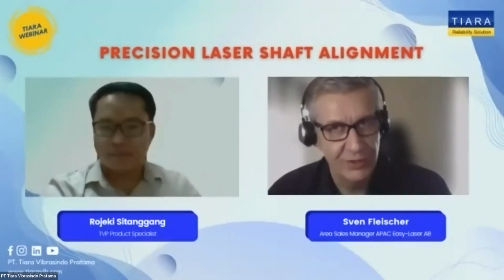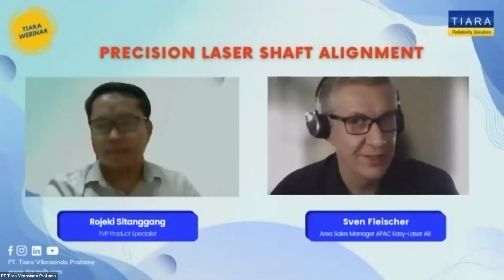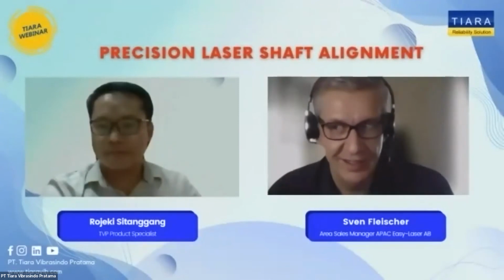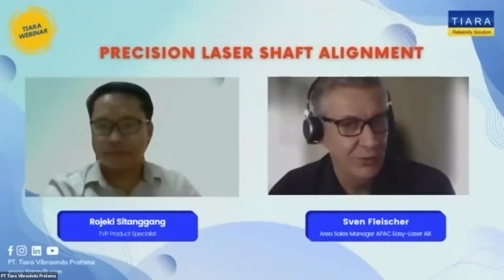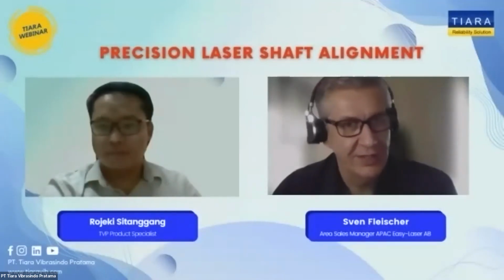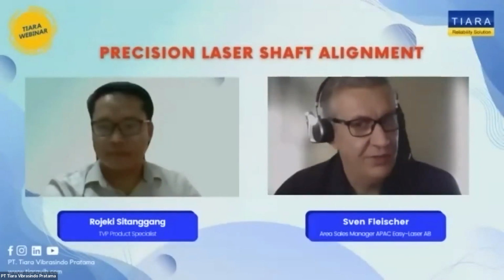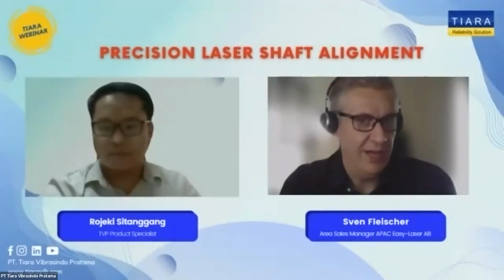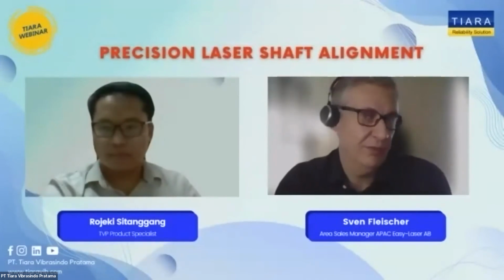Now, while you are correcting the machine, what is the purpose of the measurement instrument? It records basically all kinds of physical movements as you go towards a precise alignment. It would not know where this movement comes from. Is it from your machine correction, or does it come from another influence factor, which is a disturbance? This differentiation is not possible to make. That is then up to the engineer to recognize and then to compensate or to re-measure.